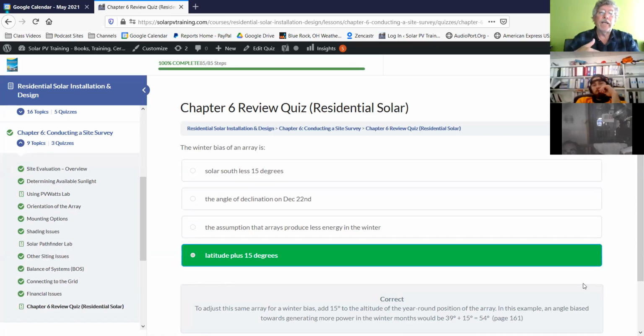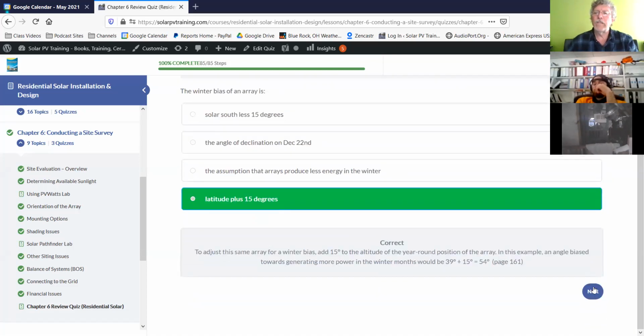So typically what you're going to find in this region of the world, in Ohio, I-70 runs right along the 40-degree parallel, pretty close. So 25 degrees is our summer bias, and that's about the angle you're going to want to set your panels, right at about 25 degrees. What you'll find is anywhere between 20 and 35, that's going to work. Not a whole lot of difference there.